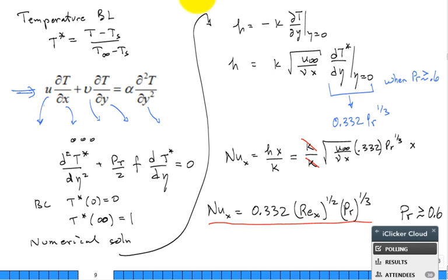And you have to introduce some abstract dimensionless temperature ratio, T asterisk, that's what the book uses. And you transform with a little work the energy equation into another equation. This equation requires you to already have solved the Blasius for the u's and the v's for the velocity profile. And what do you get? Can you just look at this equation and tell me what it looks like?